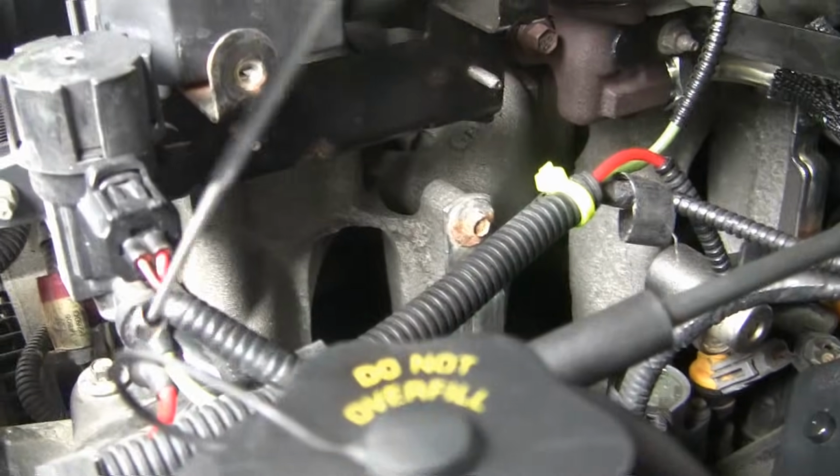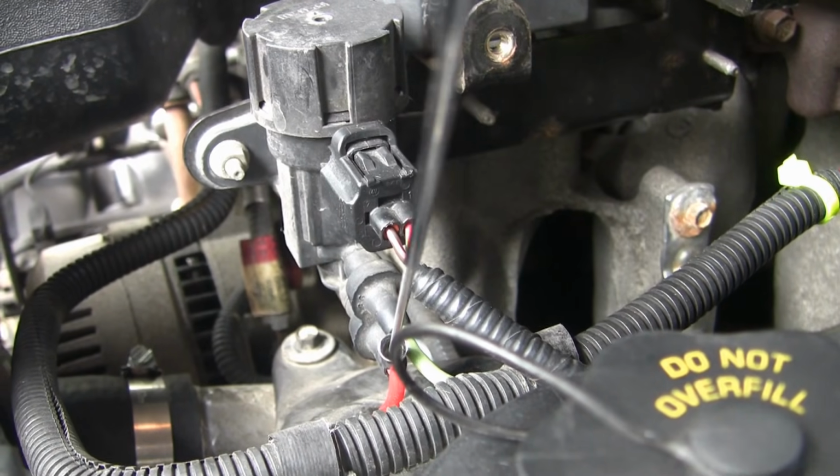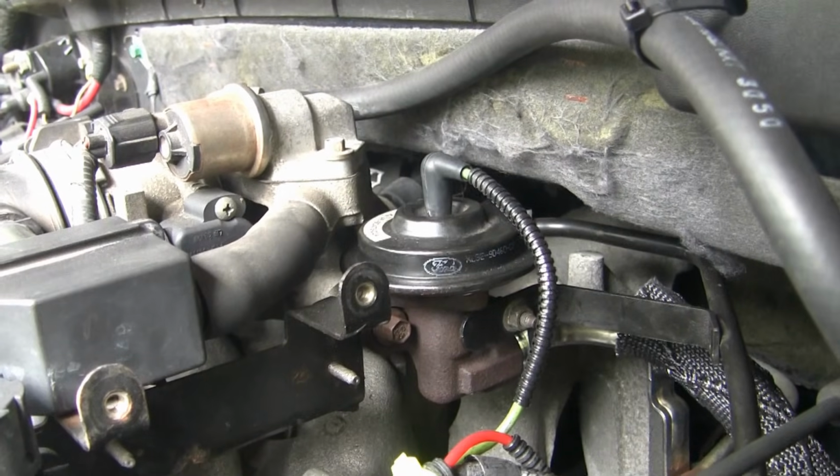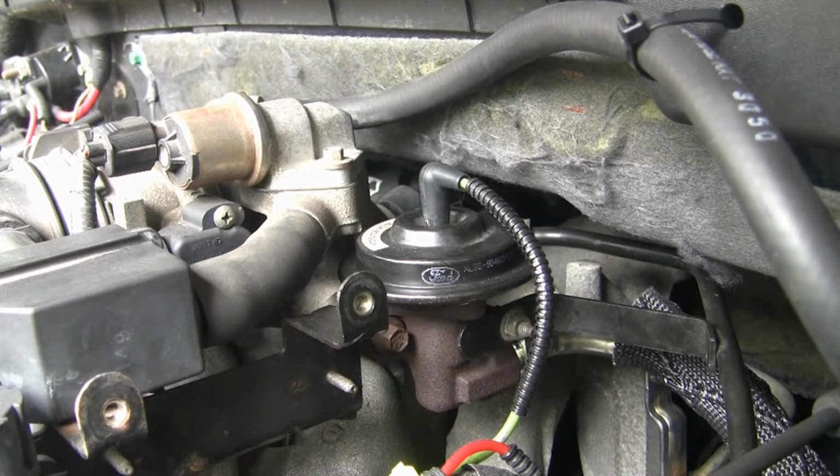The other thing you can do is, I just pop this guy off of here, and I have a little hose connector. I run the vacuum, I pull it right off this red and put it on the top. And that's a way to get vacuum right off the engine if you don't want to go out and spend money on a hand vacuum pump.